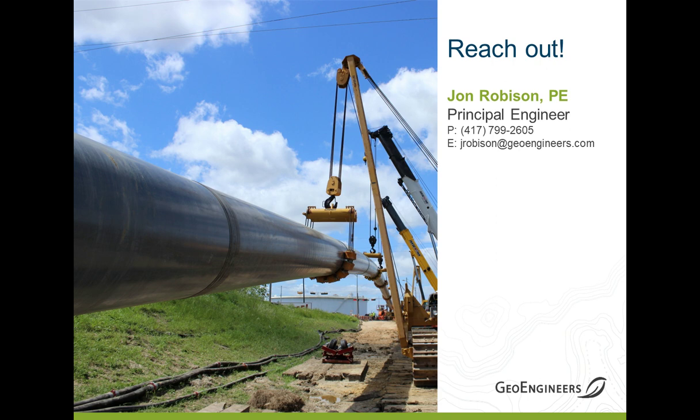Okay. As far as the conditions that the microtunneling heads can go through, can the cutter heads handle mixed face conditions such as alluvial deposits to a soft medium strength rock? Yes. It's a conventional microtunneling setup, so anything that you could think of.